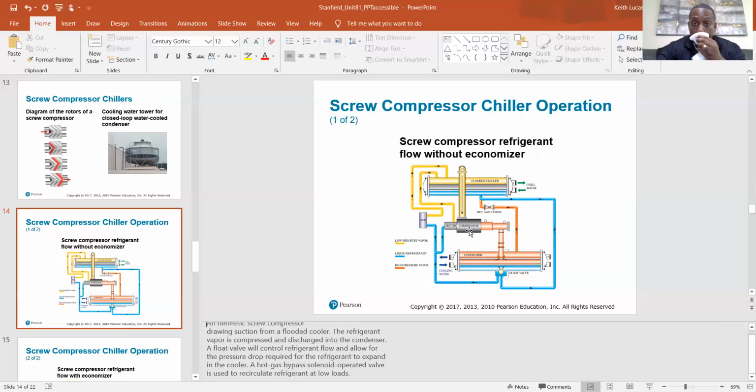Same thing. Only difference is the heat transfer is taking place between the refrigerant and the secondary refrigerant, rather than the refrigerant and the air that's being conditioned. The secondary refrigerant is the water. So the water is being cooled because the refrigerant in the evap coil is absorbing all the heat from the water and pumping that chilled water to our cooling coils, and then the heat from the discharge gas is being absorbed into another water loop that goes out to our cooling tower, where the heat is removed.